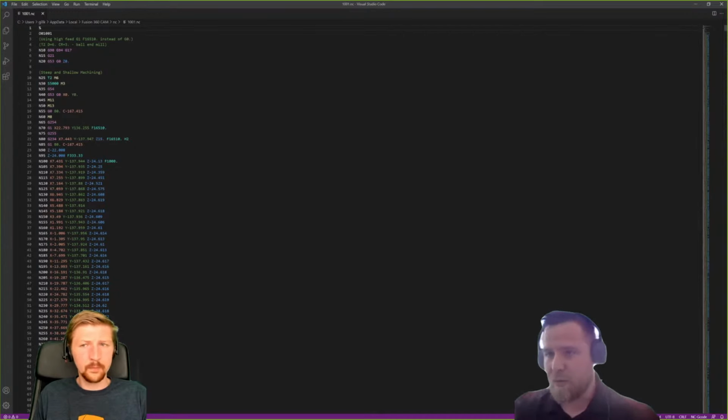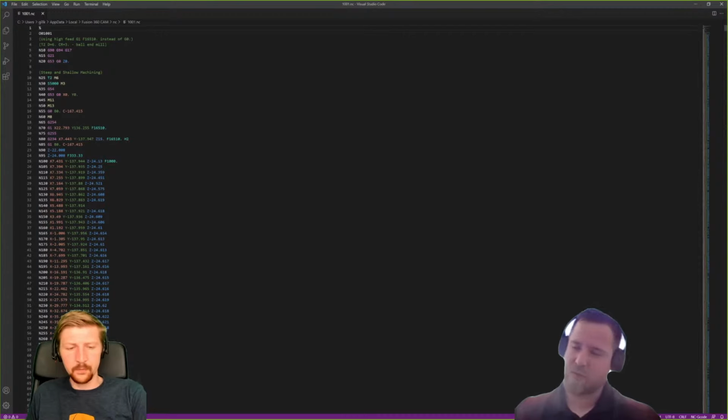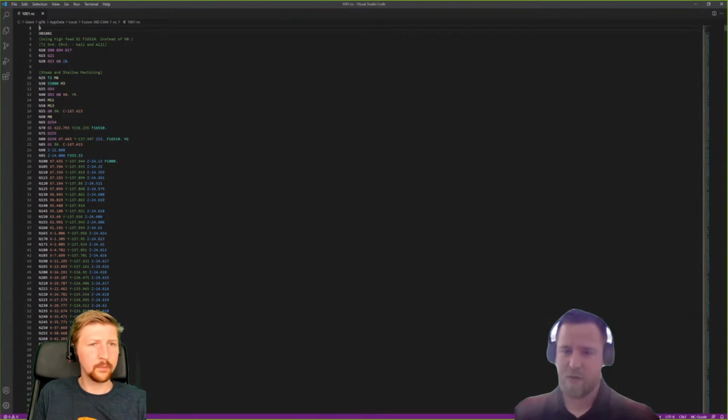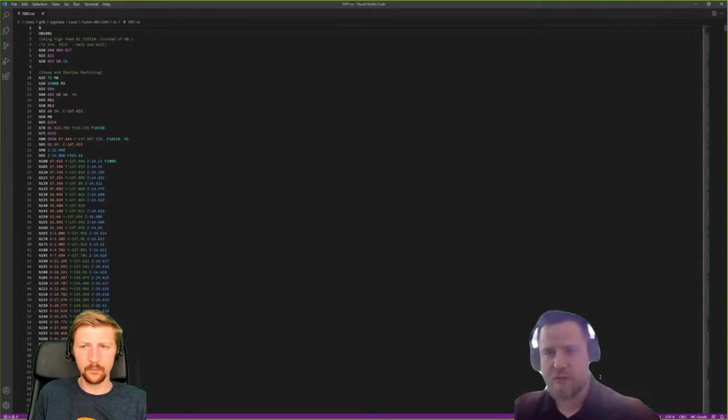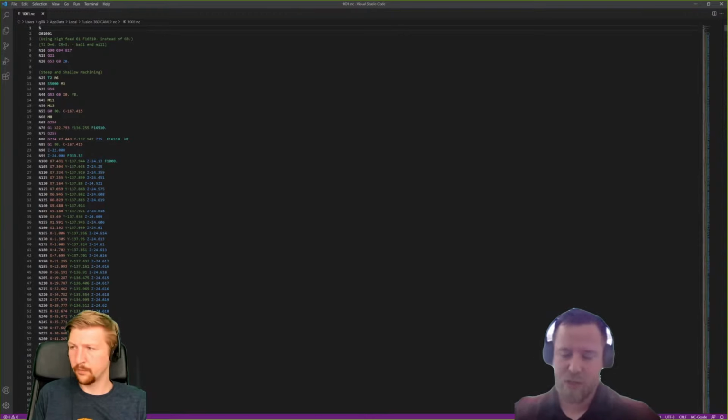So once you've tried the machine sim, you're happy with it, you know what you're doing, and you want to post it using one of the generic posts to get code out, there you go. You can use one of the online generic posts because they've been updated to support machine simulation. If you don't want to do this and you have a custom-based post, well, you have a couple of options. Either you follow the guide that Richard put the link to in the chat window, or you go to the Autodesk Services Marketplace to find someone who can help with modifying your post.